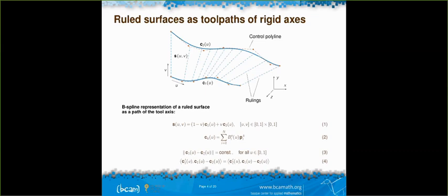Well, here, Gershon, we assume that the milling tool is always in full contact with the tool path, because what you mentioned is that sometimes the contact of the tool with the workpiece is on a smaller width, and maybe the rulings are of different lengths, if I understand you correctly. Yes, the ruling direction, exactly what you call rulings in your drawing here, could vary. They don't have to be fixed. I can have a cutter that removes different ruling lengths in different locations.